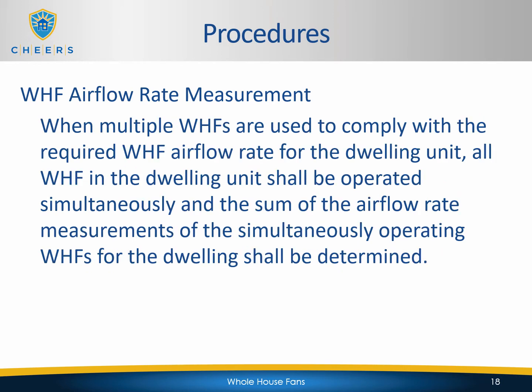When multiple whole house fans are used to comply with the required airflow rate for the dwelling unit, all whole house fans in the dwelling unit shall be operated simultaneously, and the sum of the airflow rate measurements of the simultaneously operating whole house fans for the dwelling shall be determined.